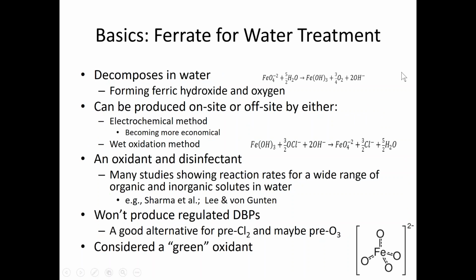First, I want to tell you about what happens when you add Ferrate to water. It's perhaps a little bit like ozone, if you're experienced with ozone, in that Ferrate decomposes in water on its own, even if there's nothing for it to react with. As you see at the top here in the chemical equation, Ferrate, which is iron once again in a very high oxidation state, the +6 oxidation state, reacts with water and forms ferric hydroxide, which is a very common precipitate that we get when we add ferric coagulants and ferric salts, and a little bit of oxygen and hydroxide.